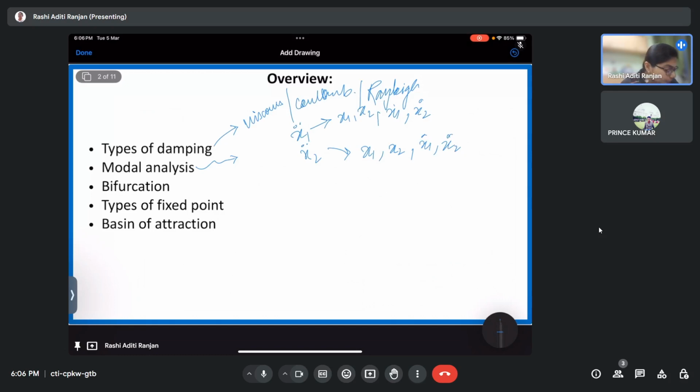But what if the equation of motion of x1 double dot also has a term related to x2 double dot? When solving a nonlinear equation, we change the second order differential equation into two first order differential equations, put it into MATLAB, and solve it using ODE routines. But if the x1 double dot equation also has an x2 double dot term, which is the differential we are trying to integrate, it is essential that we decouple the equations in terms of x1 double dot and x2 double dot, and then solve them so that the ODE function can handle it.